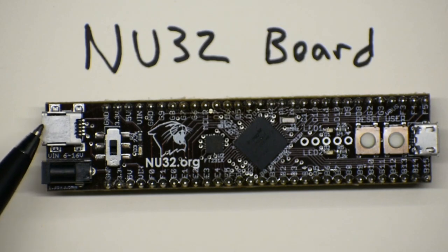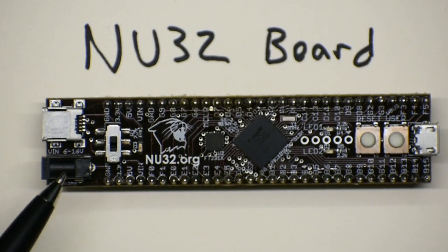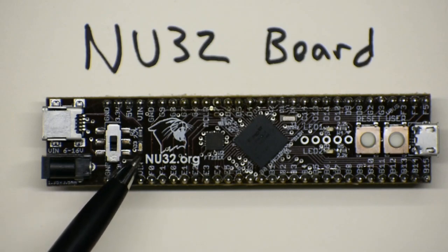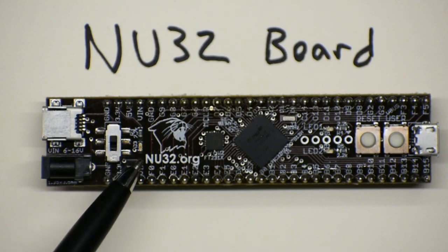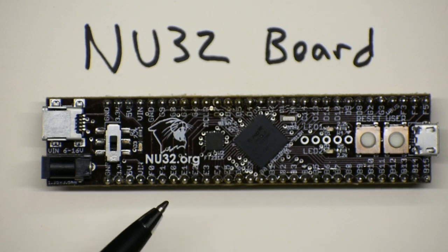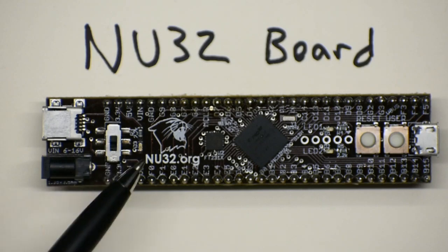So the code comes in over USB, gets turned into UART, and then dumped onto the PIC. We don't use power from the USB port, though, just in case you accidentally touch like a battery voltage to the power pin on the PIC. We don't want to damage your computer through the USB cable. So instead, all the power comes from a DC connector right here. And there's a slide switch which turns everything on, and a red LED that indicates if power is on. Should you ever turn your board on with the slide switch, but notice the red light doesn't come on, that usually means you might have a short on your circuit somewhere. So always double check your circuit before you turn it on. If you do turn it on and that light doesn't turn on, turn it off quickly before anything gets hot and burns out.